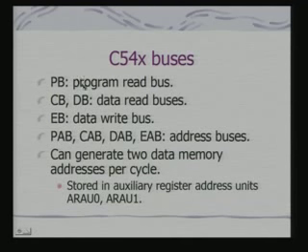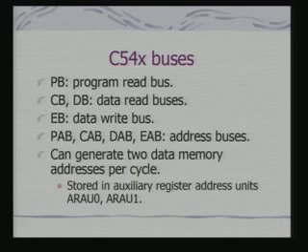And that is why, if you remember the pipeline stages, I can have instruction prefetch, fetch, as well as data address and then data fetch at different stages of the pipeline, because I have distinct buses to transfer the data and provide the address. And this is a very interesting aspect of these DSP architectures, the number of internal buses that are being supported.